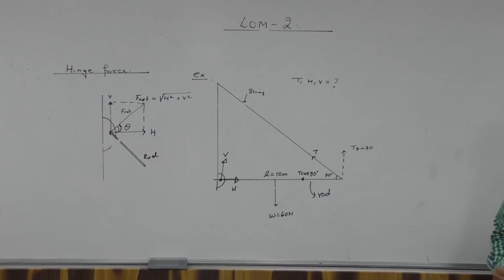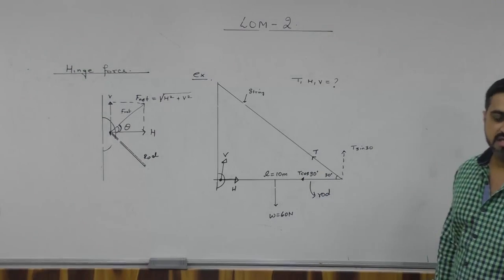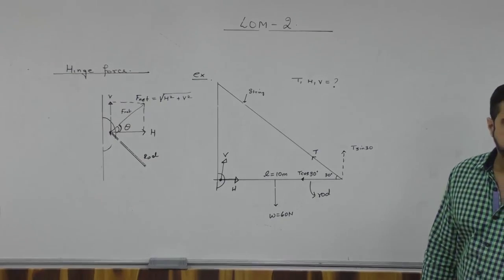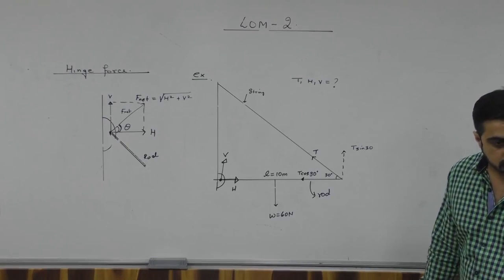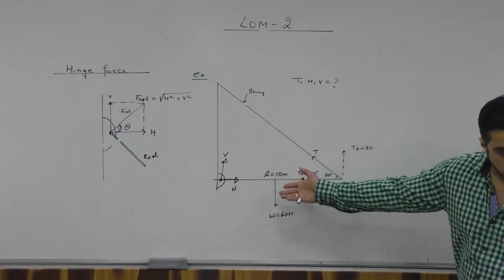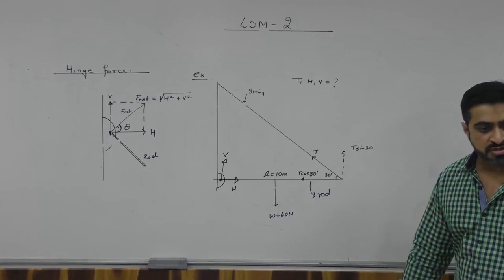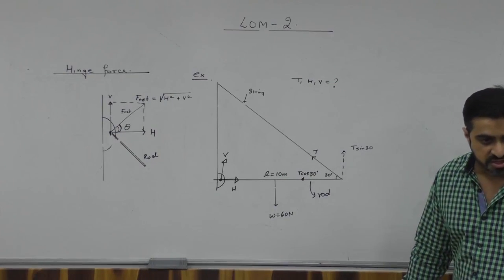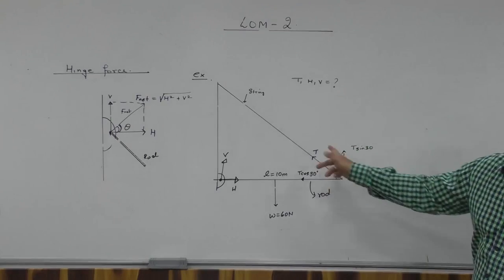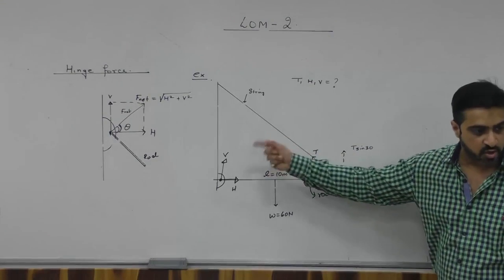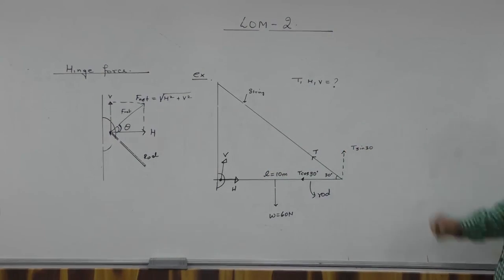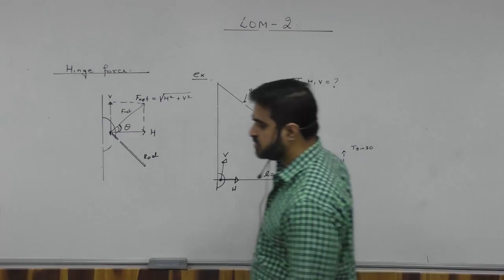Is everyone getting it? Are these concurrent or non-concurrent? Get the method. Non-concurrent. How many steps are there in non-concurrent? 3. First, up is equal to down, left is equal to right. Select any point, about that torque is 0. Right or not? You all will do? Okay, come on, start please.